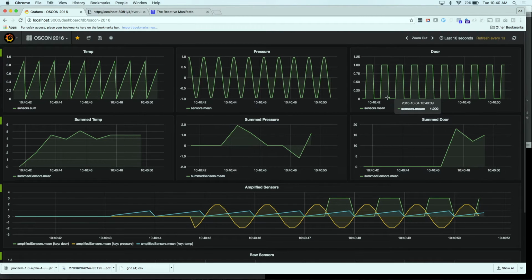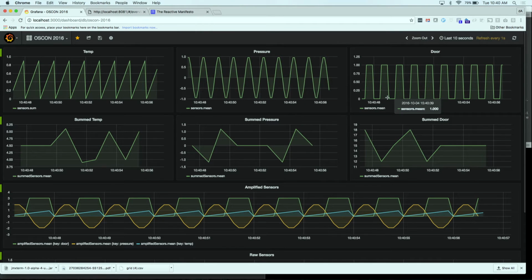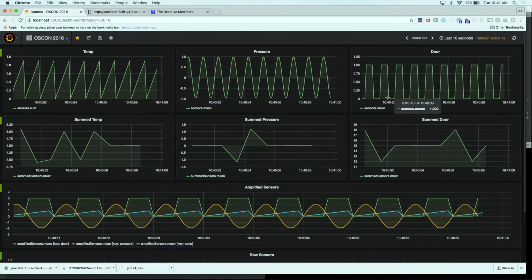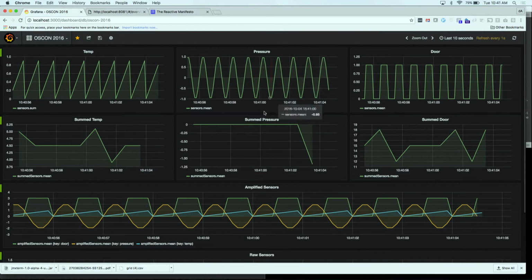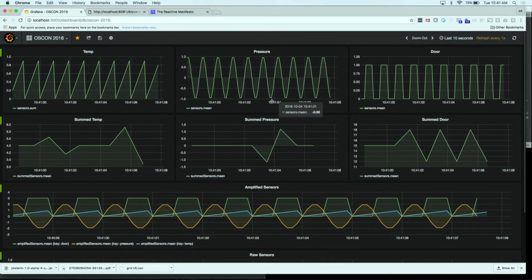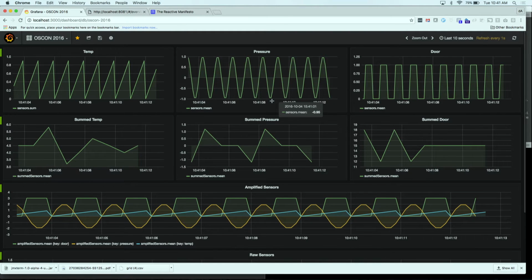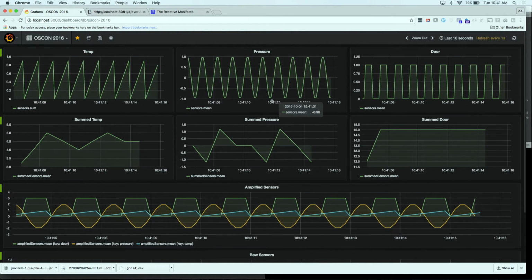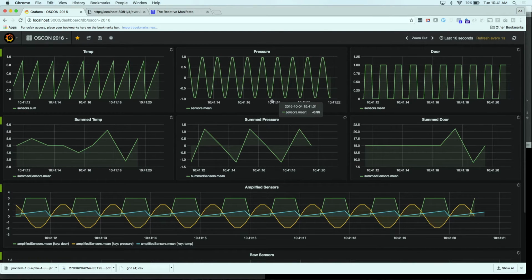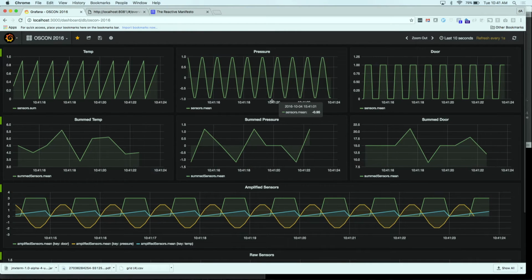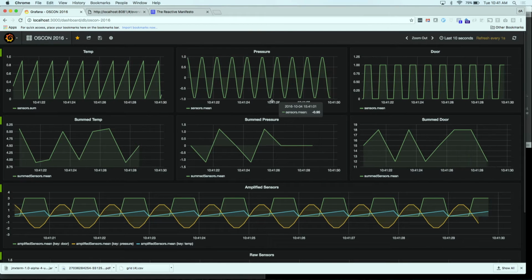Now we're summing these things up. If we look at, say, the pressure sensor in the middle, it's a sine wave. I'm going to forget about the other two for a minute. The period of that sine wave is 1 second. If you look at the code, the window I defined is also 1 second. So in theory, if I'm summing over that same second, what should the sum of one period of a sine wave be? Zero, yeah? Exactly. It should be exactly 0.